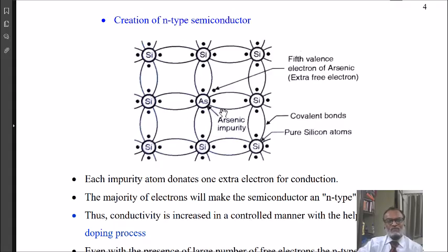That becomes 10 raised to 5 plus 100 electrons. And the specimen also consists of the free holes, those are 100. So we observe that in the doped semiconductor now there is a majority of electrons and a very small amount of holes. So in N type of semiconductor, therefore, holes are considered to be minority charge carriers.